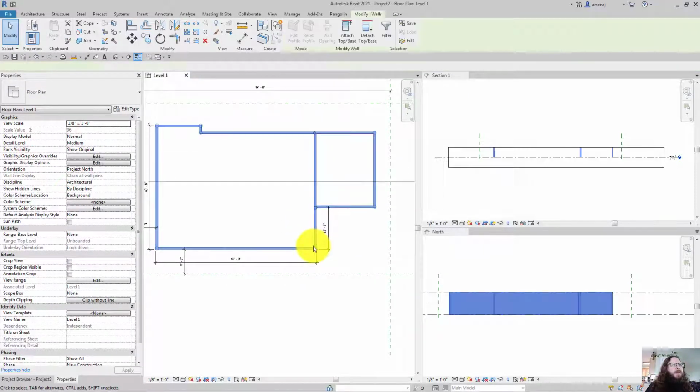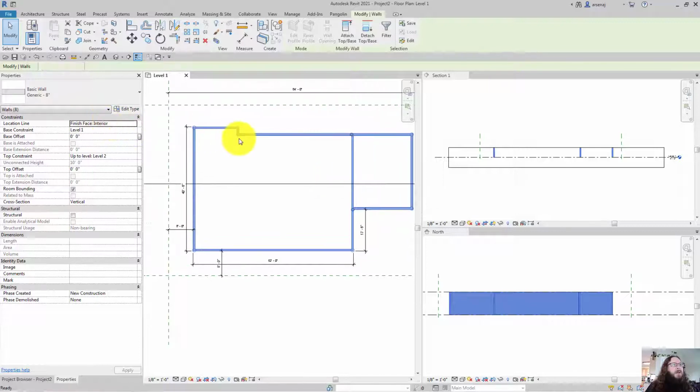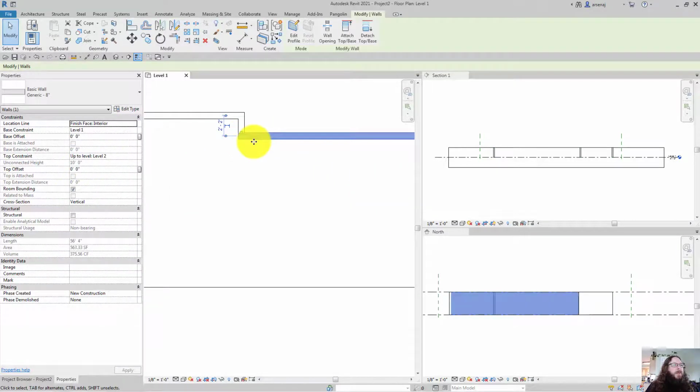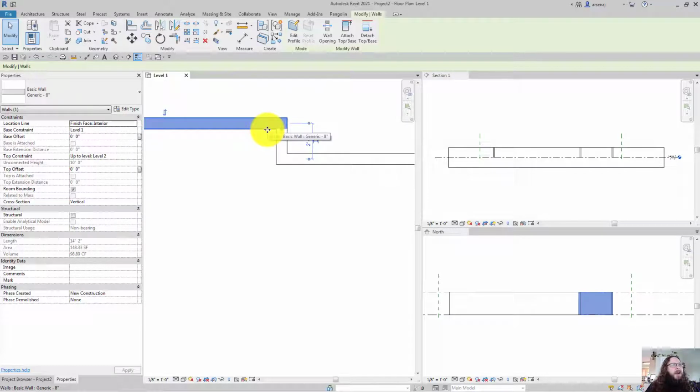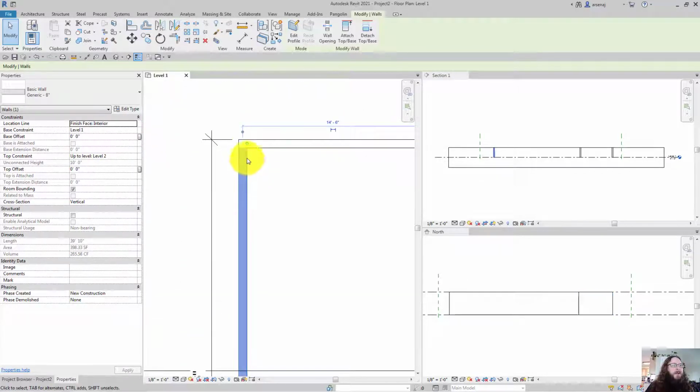And while we're in here looking at the walls, right now we have finish. The wall origin, or the location point, is finish face interior. However we drew the wall, you can see where the grips are. And right now, it looks like we've got some walls going in different directions. On this wall, it's going to start here and push its way out this way.